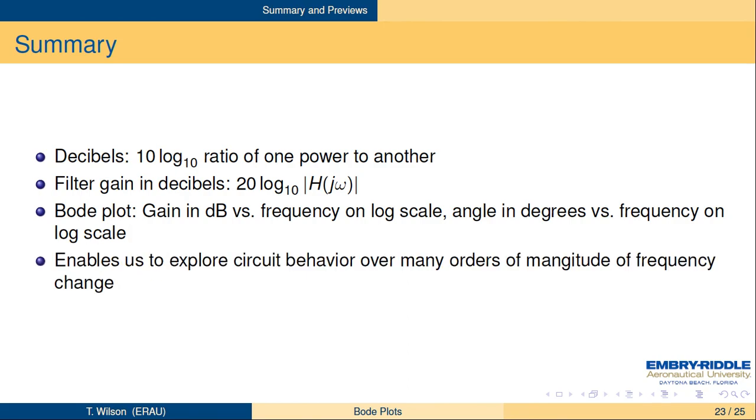It lets us look at the circuit behavior over many orders of magnitude of frequency, and we can tell the difference between small differences because of the logarithmic effect. We can also see how the high frequency behavior, which is like 1 over omega, shows up as straight line behavior on the log-log plot.